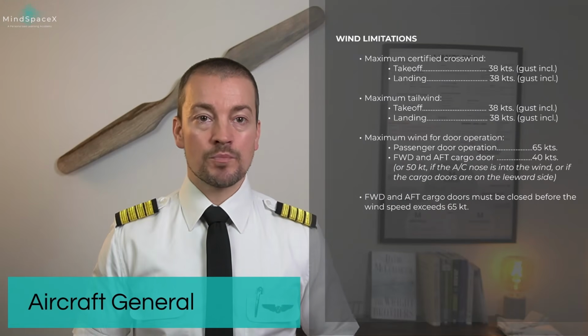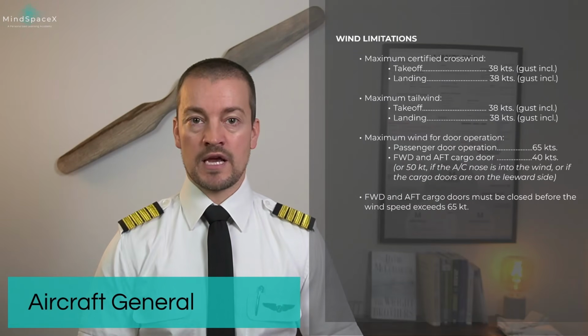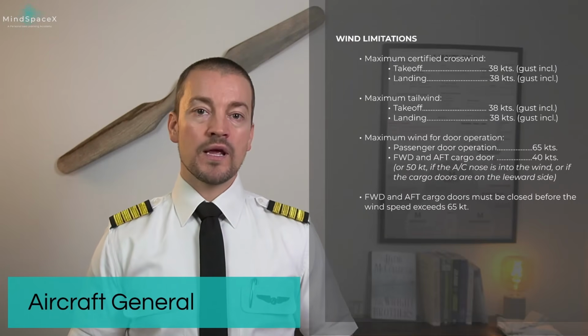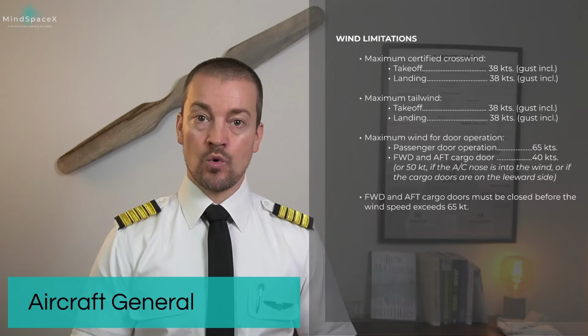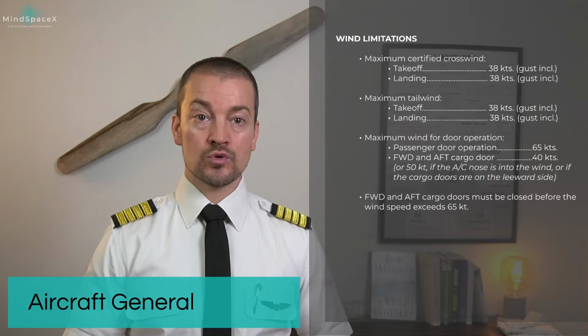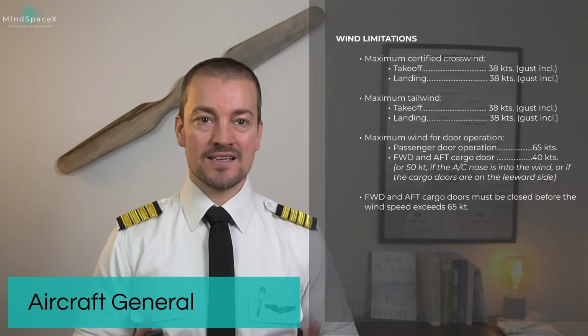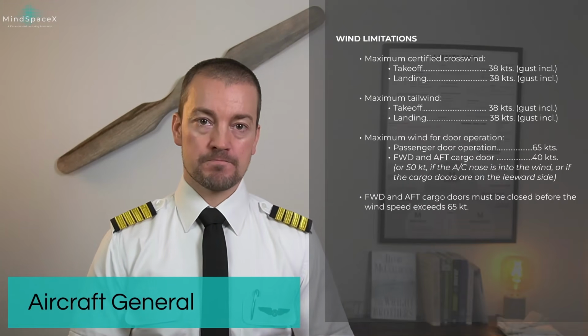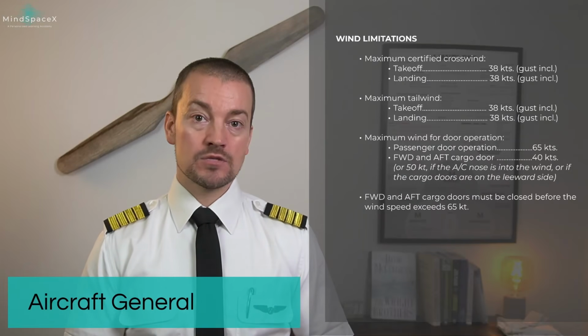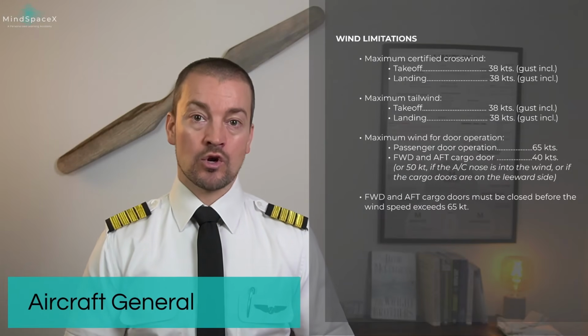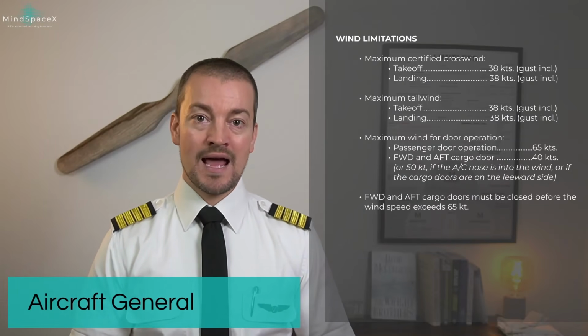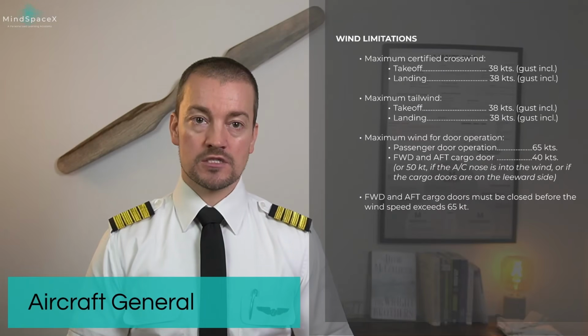Wind limitations are also placed on operating the doors around the aircraft. Maximum wind for operating the passenger door, that means opening and closing the passenger doors, is 65 knots. The maximum wind for operating, opening and closing the forward and aft cargo doors is 40 knots.